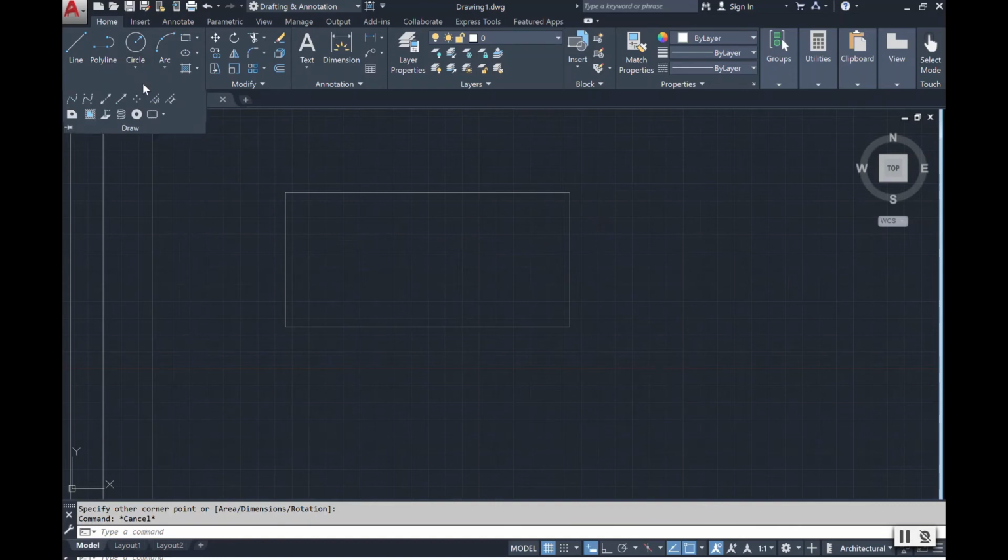For instance, I can go to my construction line and type in O for offset. Remember, this is 1 unit, so I can't offset it. Let's look at it first. If I try to offset this vertical line specifically by itself, and I haven't exploded this rectangle because I can't explode it, for some reason it needs to stay 1 unit.